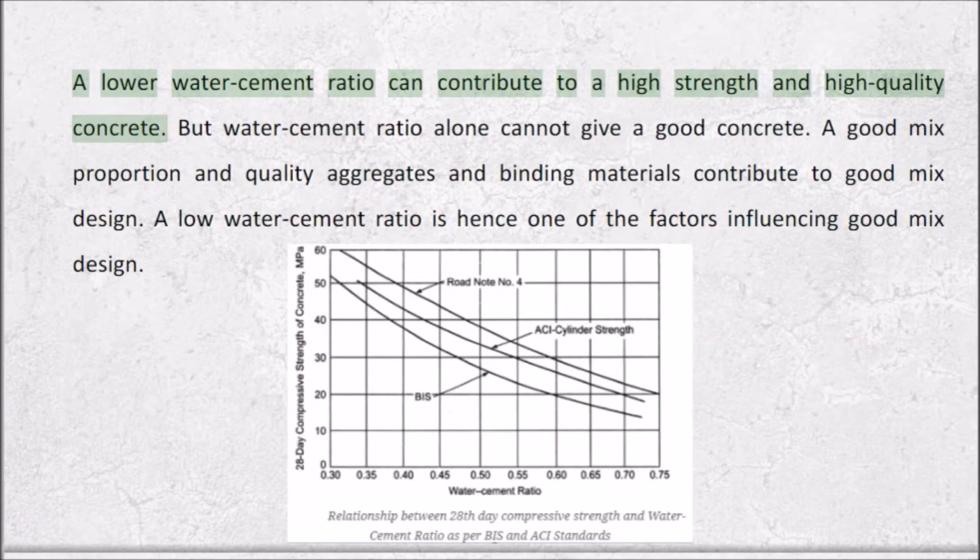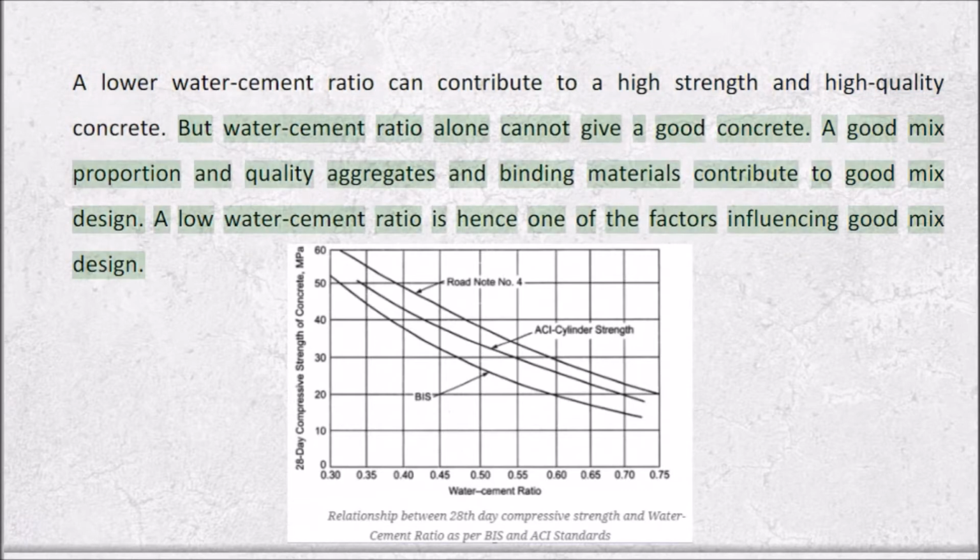A lower water-cement ratio can contribute to a high-strength and high-quality concrete. But water-cement ratio alone cannot give a good concrete. A good mix proportion and quality aggregates and binding materials contribute to good mix design. A low water-cement ratio is hence one of the factors influencing good mix design.